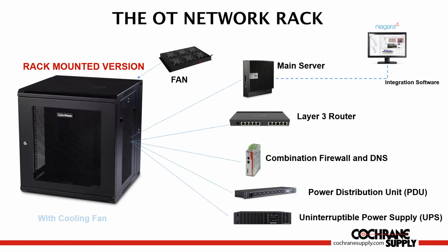So you envision a project, you go to the architect, and you say, hey, I've got this OT network rack that I want to locate somewhere. The owner's going to decide whether it's going to be in the IT MDF, one of the IDF closets, or a facility space. We always recommend a facility space. This is where your network management switch, your server, your router, your firewall, power distribution unit, and UPS are going to be located, all within this cabinet.